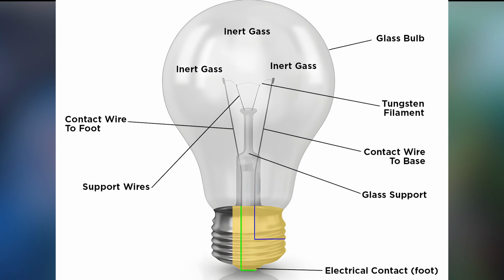So generally what's done in modern incandescent light globes is they have airtight glass enclosures. That's what the bulb is. It's just an airtight enclosure that surrounds the filament. It's often filled with some inert gas, or in the past they were also just made in a vacuum. And that's to prevent the air being ionized and other things like that happening.